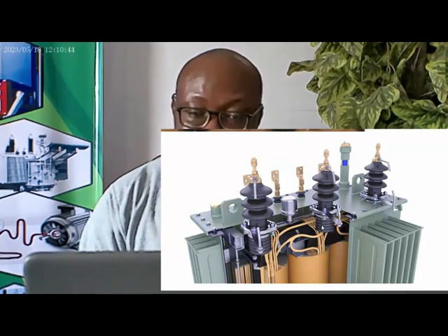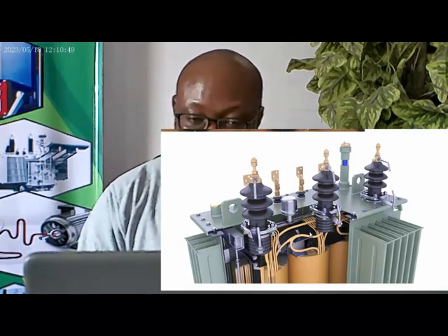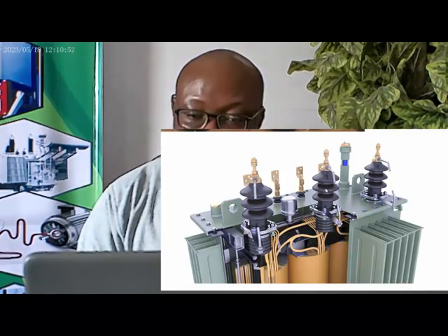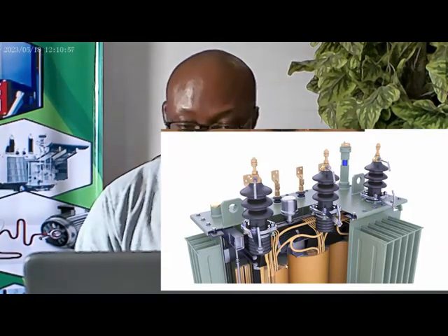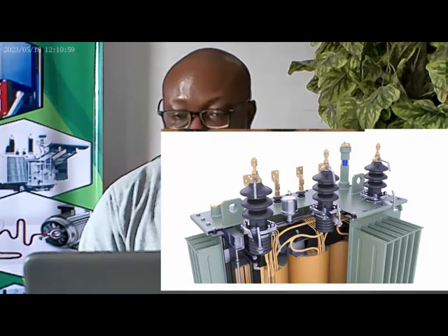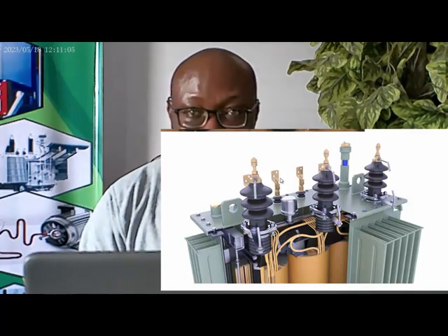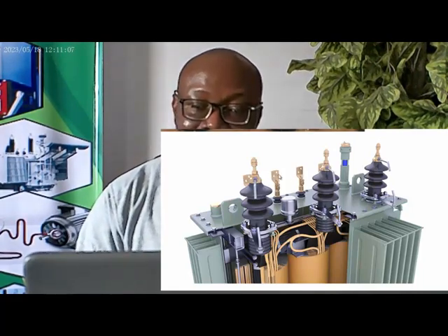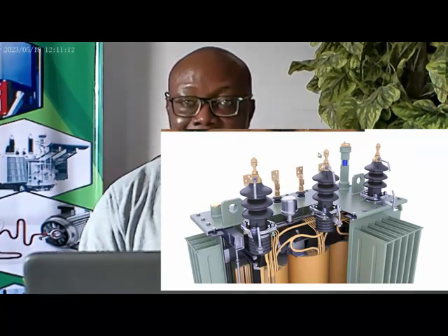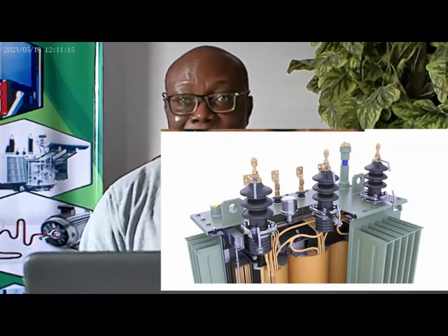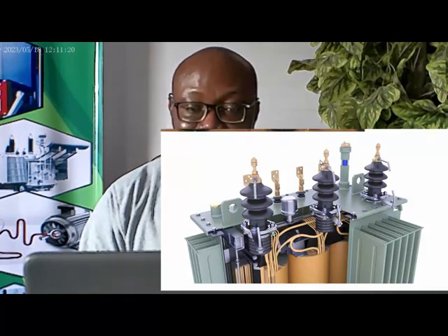So now, when you want to carry out an insulation resistance test or power factor test, as we'll see later, you will see that it depends on the connection. These three sets of windings will be delta, as we'll see later. So they have connection; they are connected internally, either star or delta. Then the primary winding has 4 terminals. If you have 4 terminals, that means it's star, as we'll see later. The common or the star point will form the neutral.